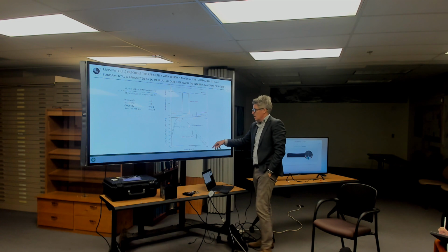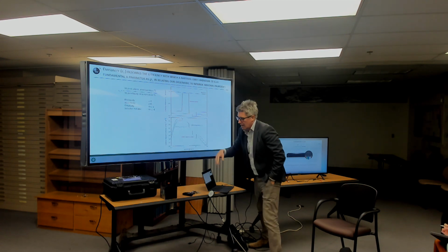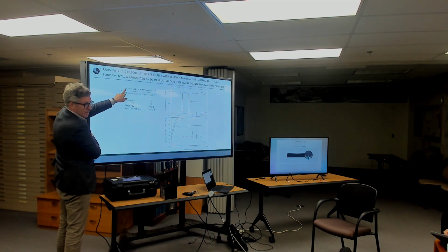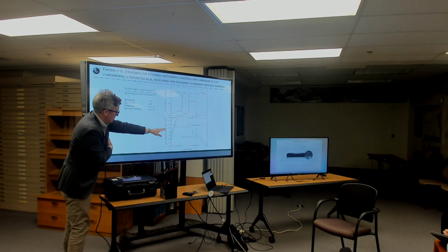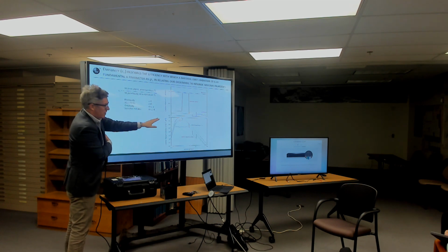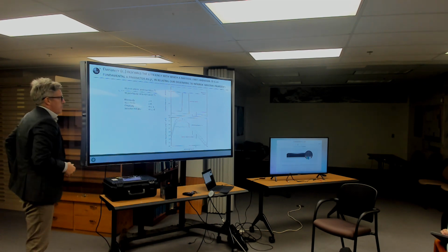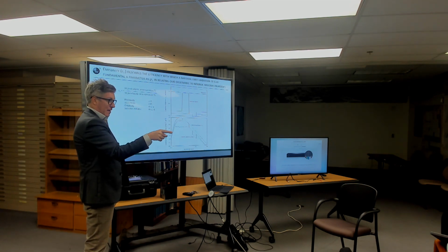Now, if that was a real object that just happened to have a really, really high emissivity, I could calculate its emissivity, right? I would take this curve at any wavelength, and I would put it on the top line of this equation, right? And then beneath it, I'd say, well, that black curve is the amount of energy radiated from a real object at 6000 K. And I don't need to do all wavelengths, I could just pick one wavelength, right? Because it's a spectrally dependent term. And then say, well, the black curve is my measurement of the radiance from a real object at 6000 K. I then say, well, what's the black body radiance at 6000 K? And I just compute it using Planck's law, right? I just put 6000 Kelvin in, and I compute it.